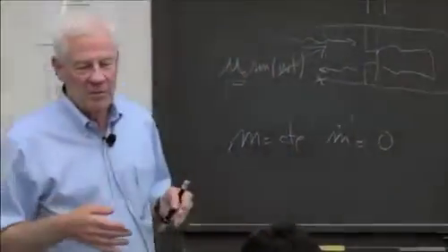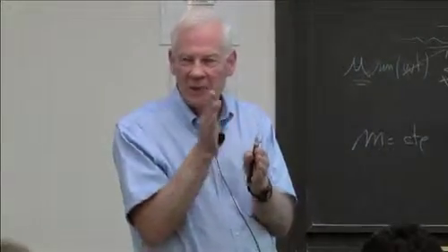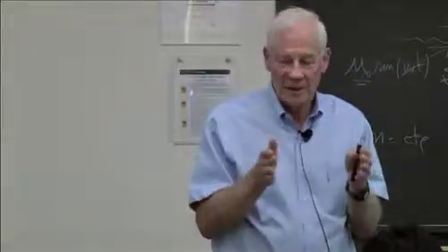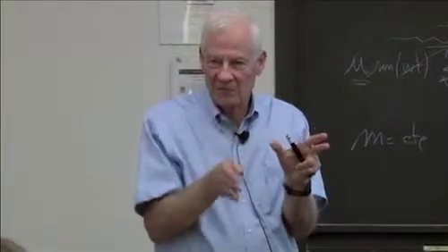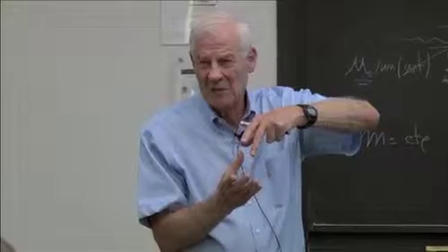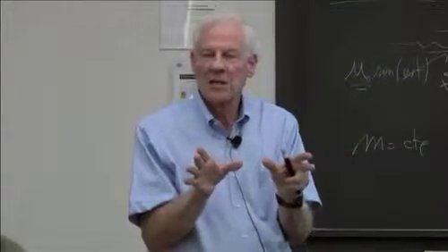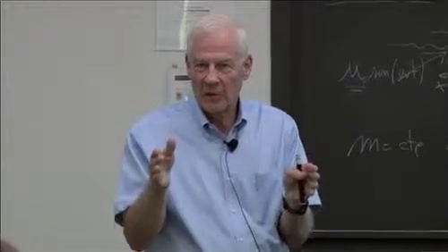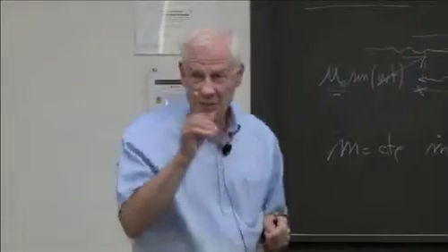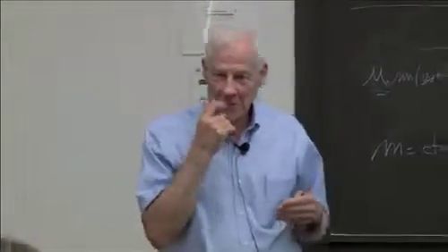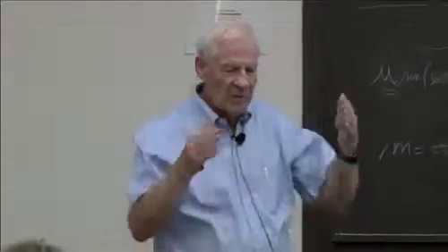So the ultimate solution, I believe, is what I call a sliding valve, and we're just about ready to try it. Took a year to get this. So we'll have it divided with a sliding valve. But our tubes are 5 inches diameter, so you can't just use a ball valve. Sliding valve. Pressurize both sides equally, open the valve slowly, fire away, make sure you understand acoustic differences. That's the way we need to do it. How have we done it so far so that we can publish some results? We use what I call stage filling. We put the mixture in we want.